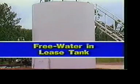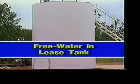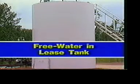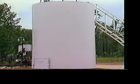Free water in the lease tank could mean the water outlet line is plugged, or a malfunctioning water dump valve. But if the valve is operating properly, it could be a sign the treater simply can't handle the amount of free water produced. Perhaps a free water knockout unit needs to be installed upstream from the treater.